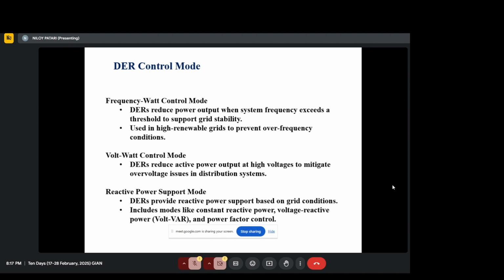Whatever we have been doing right now in OpenDSS is steady state power flow analysis, right? Steady state meaning that loads are fixed, everything is fixed, there are no transients happening, just solve power flow. But in real time, you have a lot of dynamics going on in the system. Active power, reactive power, loads are always changing. If you don't stabilize the grid under such dynamics, then it's very hard to operate it, right?